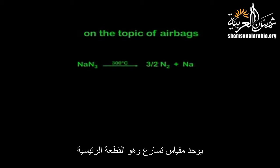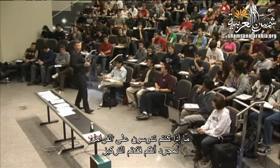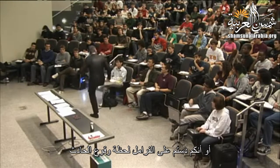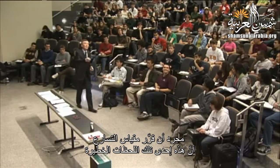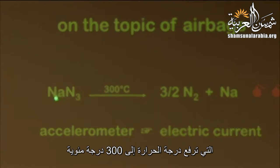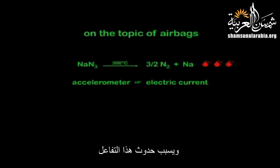There's an accelerometer, and this is a key piece. The accelerometer has to make a decision whether you're applying the brakes just because you lost focus and had a jerky brake, or maybe this is one of those holy mackerel moments and you're jamming on the brakes and we better deploy the airbags. Once the accelerometer decides that this is one of those moments, it sends an electric current through a wire, which then raises the temperature to 300 degrees C and causes this reaction to take place.